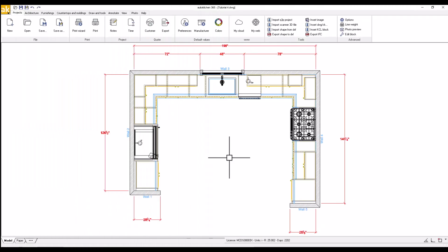Placing the kitchen island. Next, we are going to place an island which will include some cabinets, panels, and moldings as part of the design. The island is going to include a 36-inch base cabinet centered across the sink and 2 smaller cabinets on either side. The island countertop is going to be extended back to create a sitting area.